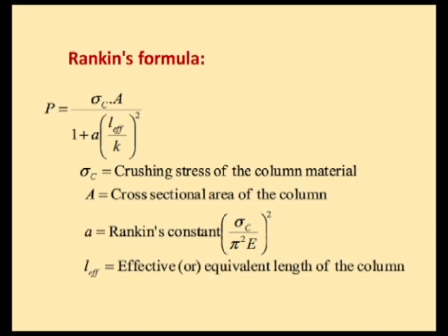So, Rankine has evaluated a formula for computing the load that can be carried by a column as sigma c into capital A by 1 plus small a into L effective by k whole squared. We will see what the terms are. If you are interested in calculating the critical load by Rankine's formula, we need to be familiar with the factors involved.